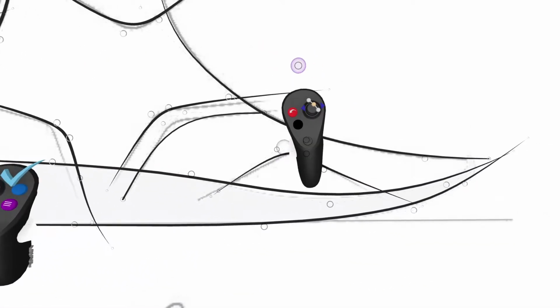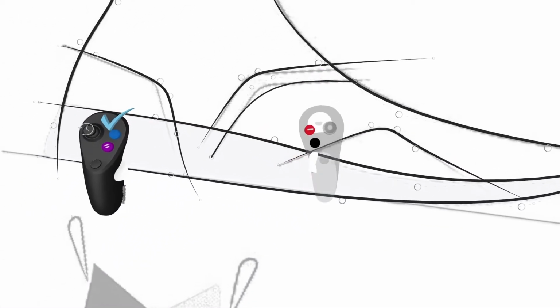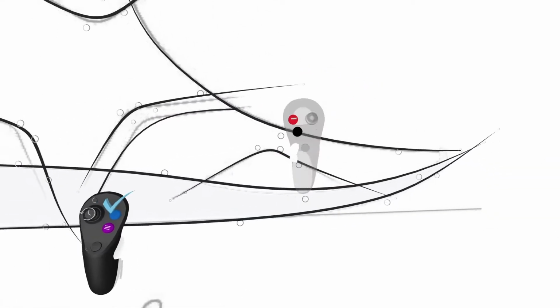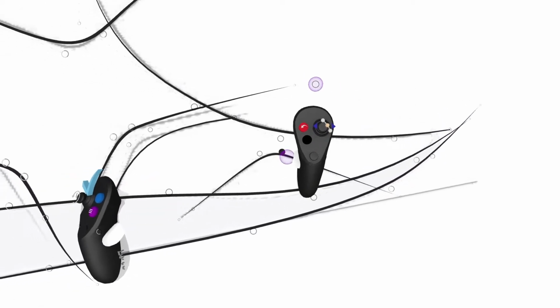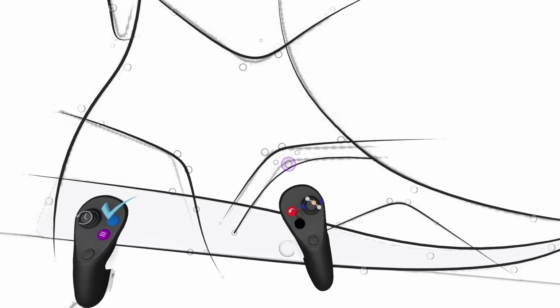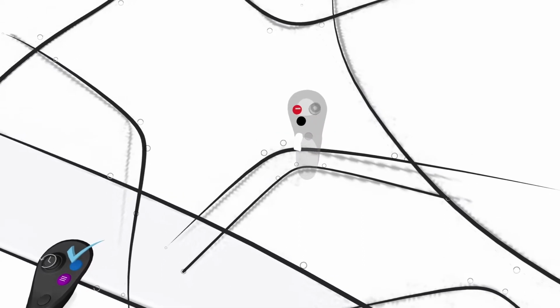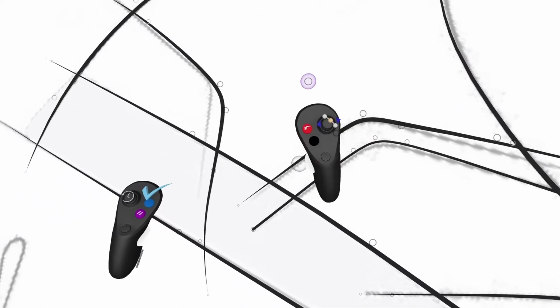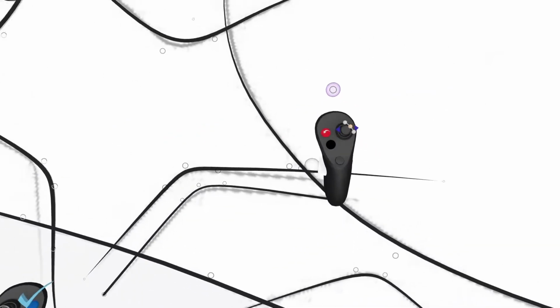Let's do this little detail here. The great thing is that when you have planar on, when you're in editing mode, it stays planar, right? So no matter what I do, I won't pull it off the plane. This helps tremendously for the setup and getting everything just as you might want it. Let me add another point here, actually. Get a tighter radius. Kind of want these two lines to have similar point count, and you'll see why that's important later. So do our best to do that as well.